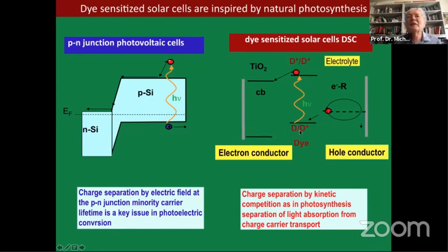And so the molecular photovoltaic approach goes away from the p-n junction, and in the dye-sensitized system, we use a molecular dye. So the dye gets excited, the electron is injected into an oxide with a large band gap like TiO2, and that's a charge separation. You have a negative charge in one material, the oxide that carries the electron, and we have the positive charge on the dye. So now we have to collect those charges, and that makes a photovoltaic device.